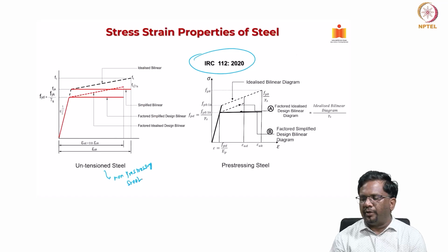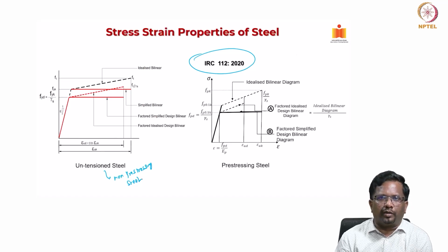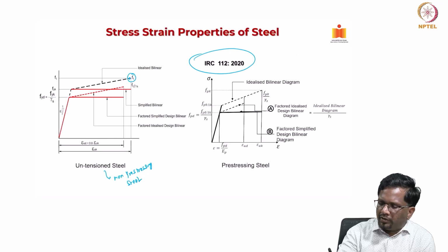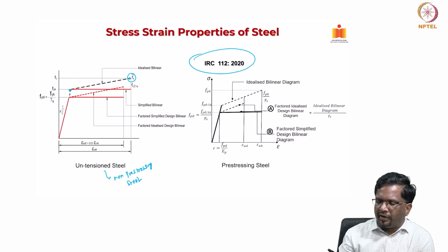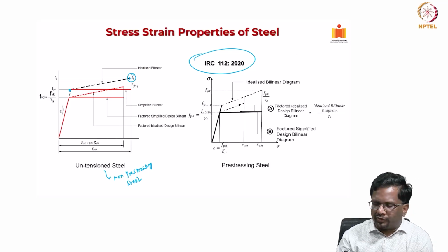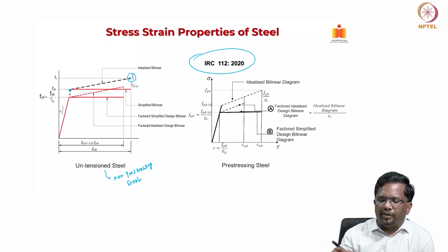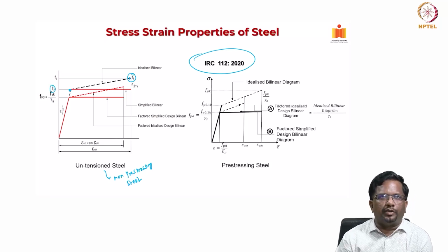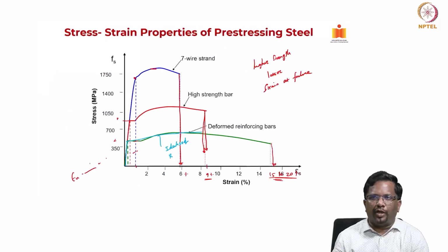Now, you see here there is a black color curve. This is for a regular rebar. You get what is called the ultimate tension strength and what is called the yield strength, and typically we take it at 0.2% proof stress, right. So, then we get the yield strength. Fyk is the yield strength, Ft is your ultimate tension strength.